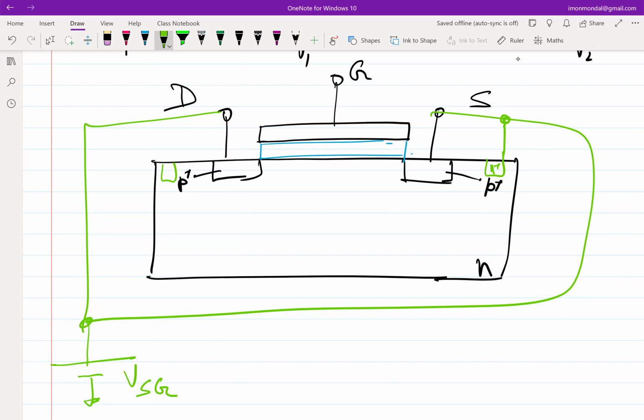Right? So let's further assume that you have some voltage between the gate and the body. The gate is also connected with respect to the source at a lower voltage, because ultimately what you want is some voltage so that these electric fields appear.